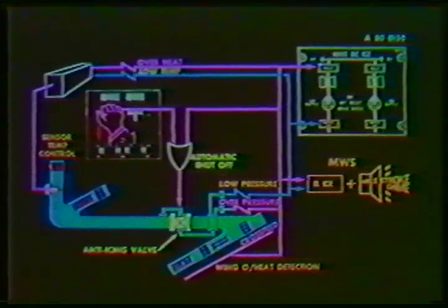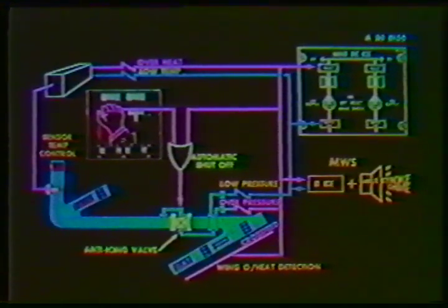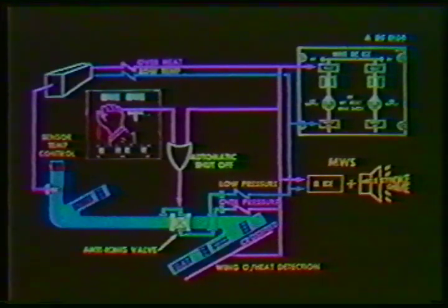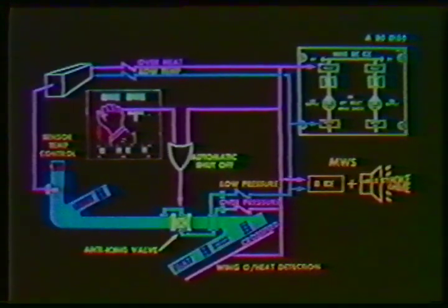A supply low light on the control panel will illuminate along with the de-ice light on the master warning panel, and a single-stroke chime sounds when low temperature or low pressure is sensed in the wing de-ice duct. This action does not close the wing de-ice valve.